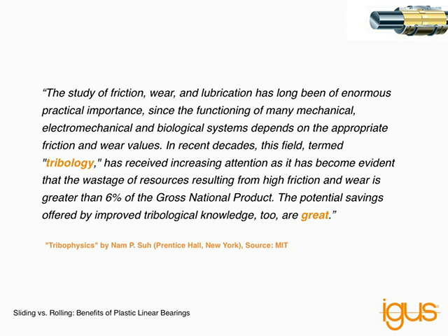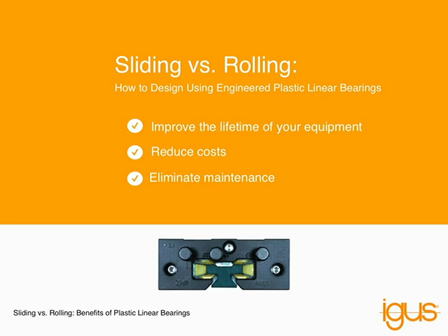So with that, I'd like to start today's webinar. The topic of today's webinar is sliding versus rolling. We're going to discuss how to correctly implement plastic linear plane bearings into applications where perhaps you're more familiar with designing recirculating ball bearings. This is a way to help you improve the lifetime of your equipment, reduce the cost, and eliminate the maintenance from your applications.